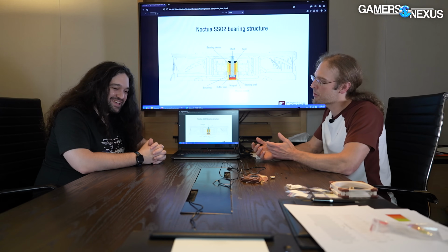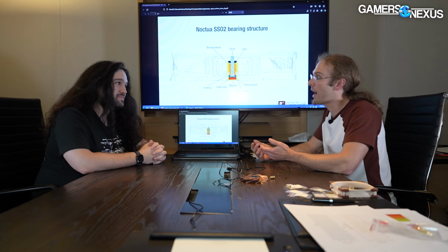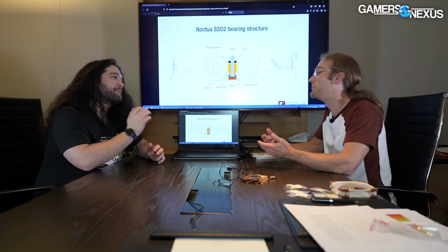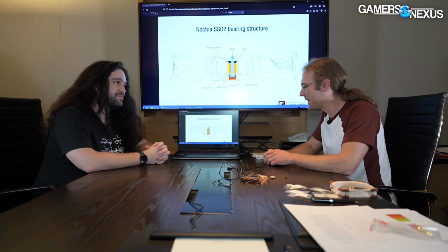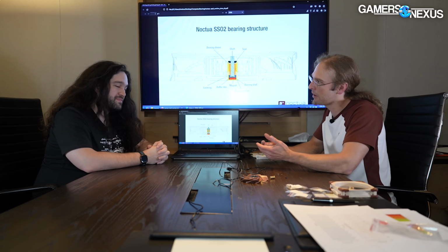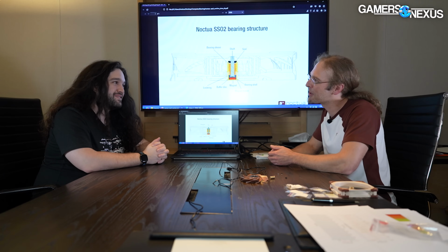From a technical perspective, first of all, FDBs and HDBs, I would say the terms are interchangeable because hydro is just water in Greek, and fluid is obviously fluids in Latin. So I would say these mean the same thing. And if companies try to distinguish between the two in marketing, it's more a marketing endeavor than a technical difference. From a technical perspective, fluid dynamic and hydrodynamic bearings are sleeve bearings. If you say, okay, what I mean by FDB is that it has that herringbone or spiral groove, that's a different story. Of course, you can make that distinction.